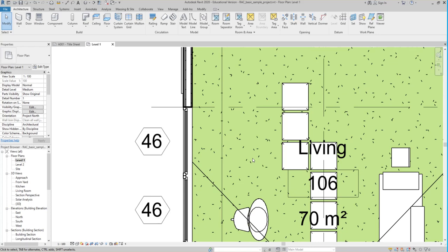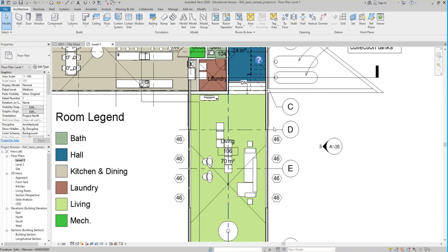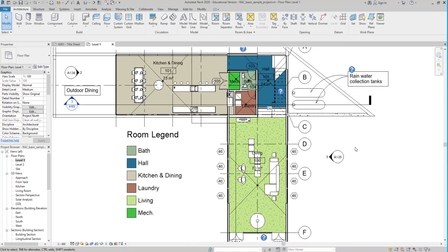So when you look at a set of drawings, immediately the first thing you should see is that thickest pen weight, which is going to be, we'll call the most important architectural elements, okay? So when we print this set of drawings, we want the most important architectural elements to be the thickest pen weight, so that when somebody looks at it, they can immediately and visually recognize those items, okay? So walls, doors, windows. Things that sort of enclose the space are the structural pieces of the building. We want those to read the heaviest, okay? So the most important elements are the thickest elements, okay? Doors, walls, and windows. Great.